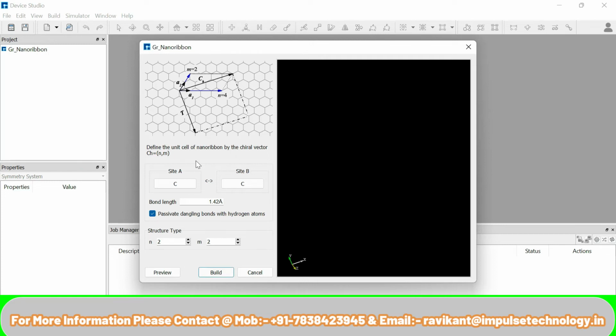A new window has opened where I can define the type of element that I want to use for the design here. I can define the bond length of my passivations of dangling bonds. I can activate this checkbox and define the chiral vector as per your requirement. Let's suppose I take the default one and click on the Preview button.